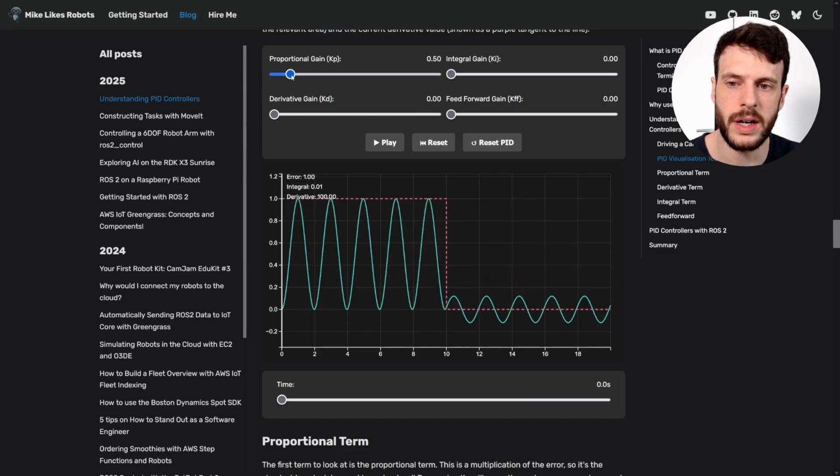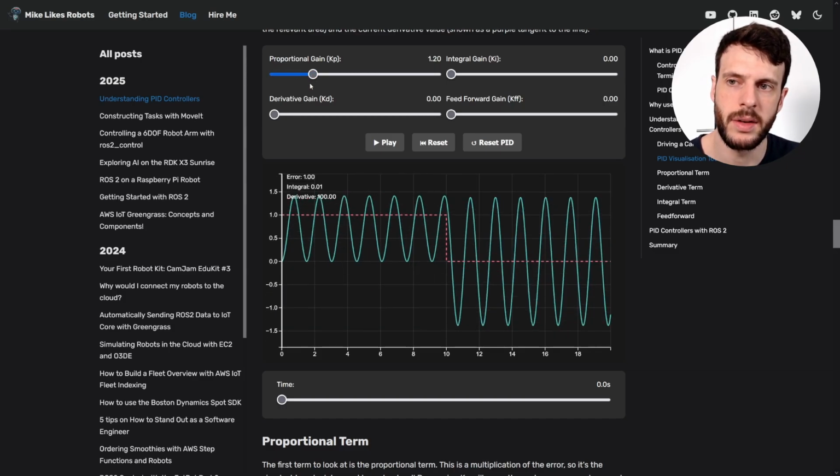You'll see this a lot in control systems: when you put too large of a P term on, it overshoots. Just as with our car driving example, if you accelerate too fast, you can overshoot the line. The same is true of a lot of control systems. If you increase kp too much, it will overshoot the line and oscillate around it. Thankfully, this is where we can add the second of our terms. I'd recommend just going with the derivative term, because adding integral makes the graph go crazy.